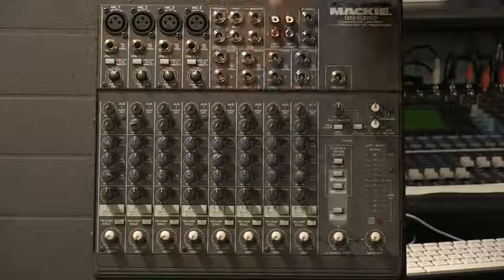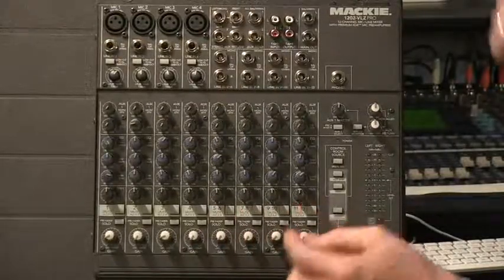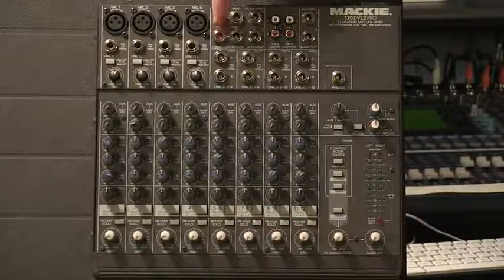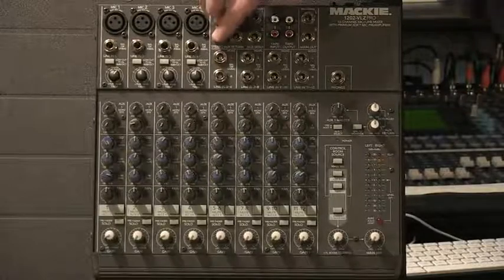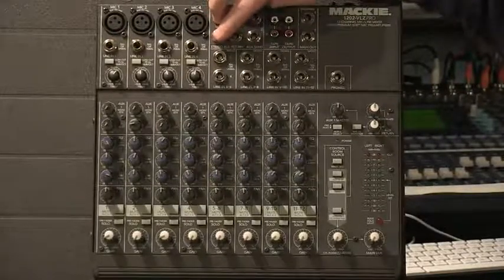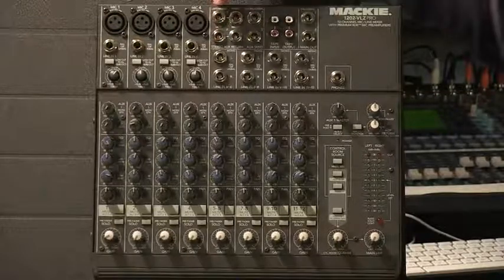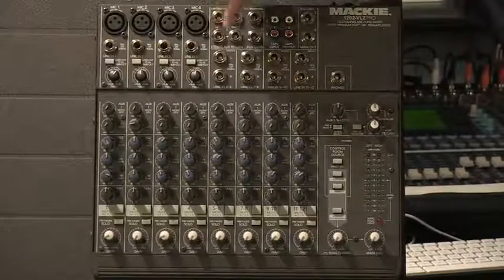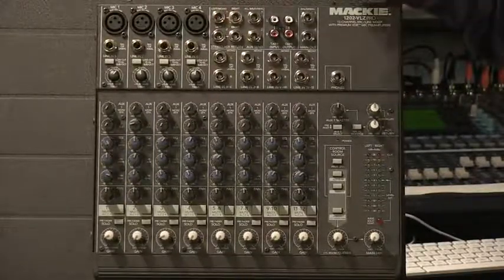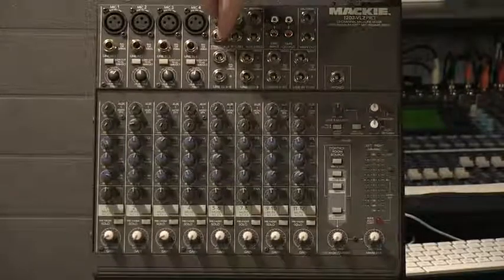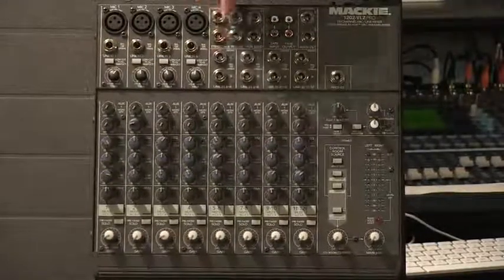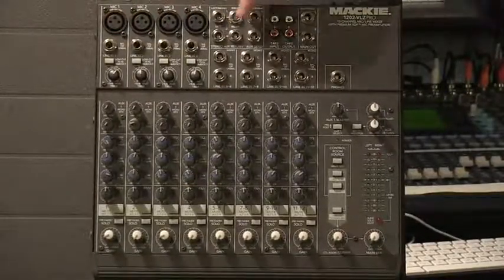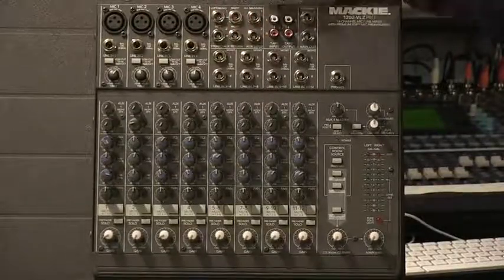Over here in channels 5, 6, 7, 8, 9, 10, 11, 12, you will see we only have one volume control down here. But these are designed so that we can plug in any kind of 1/4-inch phone plug that already has a stereo output on it. So if you have a stereo system, a CD player, an iPod, an external sampler or a synthesizer, anything that's generating stereo information, usually a device that has a 1/4-inch phone plug or 2 of those, you plug in here. So we have a left and right channel that we plug in, but that's still 2 channels of information. So in total this particular mixer gives us 12 channels of information, even though these are designed to be coupled with the left and right inputs on them.